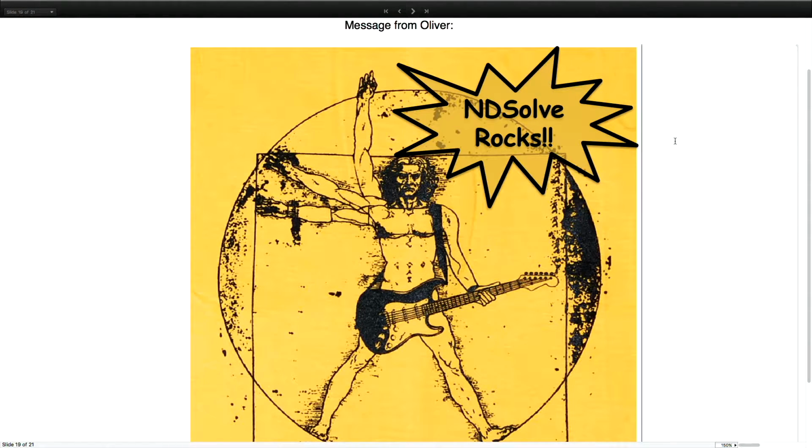The derivatives of the response are actually more accurate at the Gauss points than they are at the nodes. That concept is very common throughout that whole world, structural mechanics and crack analysis. So can we get at that data, the derivative evaluated at the Gauss points, the most accurate spot in the domain?